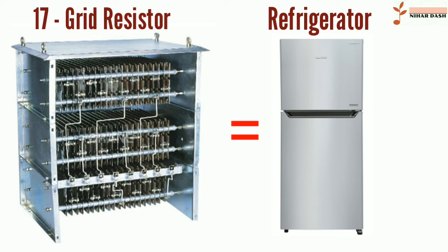They are used in applications such as dynamic braking and load banking for locomotives and trams, neutral grounding for industrial AC distribution, control loads for cranes and heavy equipment, load testing of generators and harmonic filtering for electric substations. The term grid resistor is sometimes used to describe a resistor of any type connected to the control grid of a vacuum tube. This is not a resistor technology, it is an electronic circuit topology.